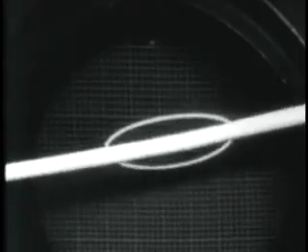Now, why is this oval lying more on its horizontal axis than before? Well, once again, remember, the two voltages are not equal in amplitude. In this case, EC is only 10 volts, and EA is 26 volts. So we do not have equal amplitudes. However, the phase is indicated by something between 45 and 90 degrees.